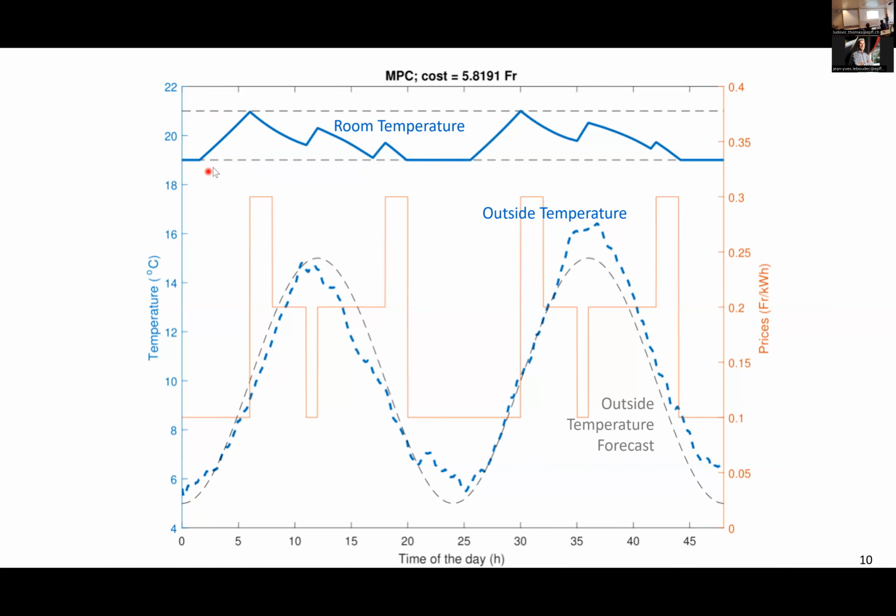We see that the control was perfect in the sense that even though it's a soft penalty, the temperature was always within the deadband. This is because I put a very high penalty value to being outside the deadband. We can observe here the desired behavior.